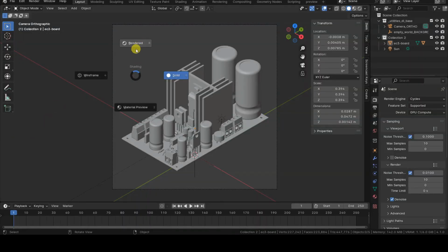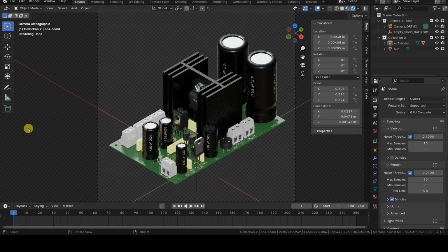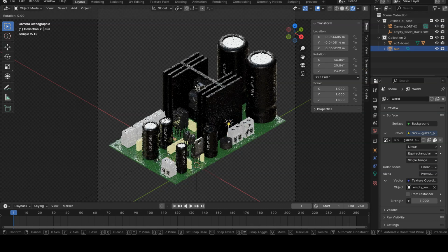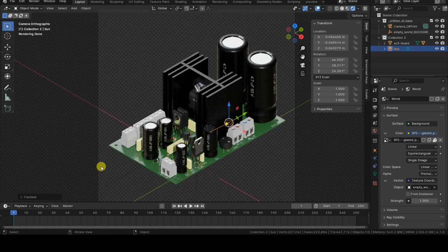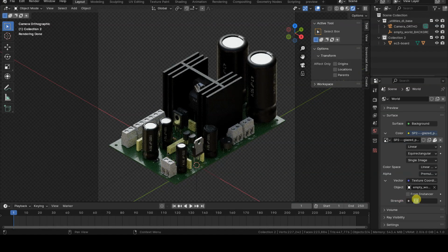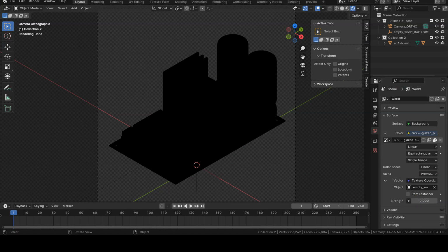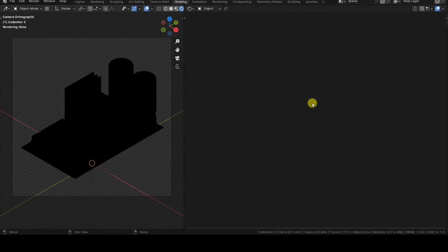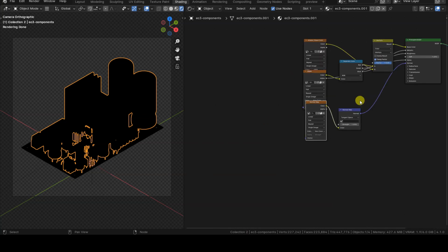The first thing to do is to disable the scene's lighting. The initial PBR rendering was created with an HDR texture on the world background and a sunlight source. But in this case, the object itself will act as a light emitter to provide uniform shading to all parts of the object. Therefore, delete the existing light sources in the scene and set the world lighting intensity to 0. In a rendered preview of the 3D view, we won't see anything, precisely because there is no light source in the scene.